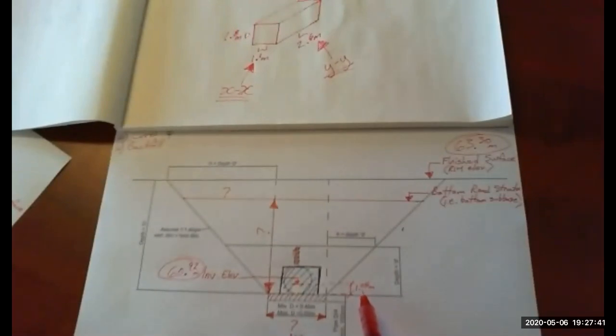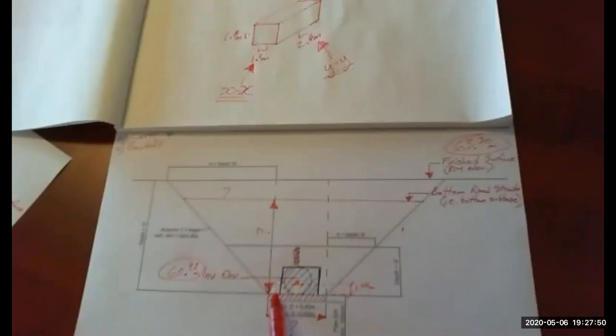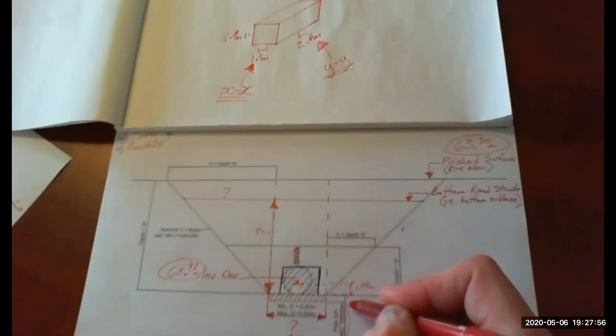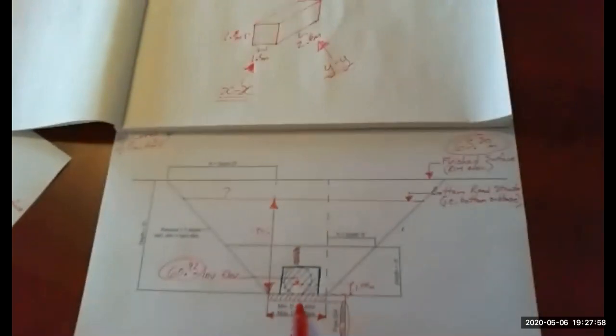It adds an additional 1.05 meters to your excavation depth. So let's calculate this depth here. And then we're still using 100 millimeters minimum for this bedding layer. So for us, we're always going to have 100 millimeter thickness down there. So let's calculate this overall depth here.